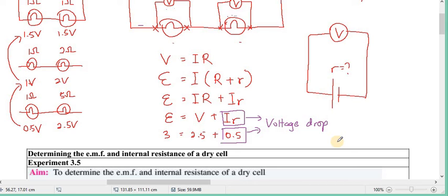But when you turn on this fan, this is the furthest electrical appliance, the furthest away from the switch. Can it get 240 or not? No, it will get less than 240. Let's say it only gets 230 volt. That means short by 10 volt, right or not? That 10 volt is what we call the voltage drop.